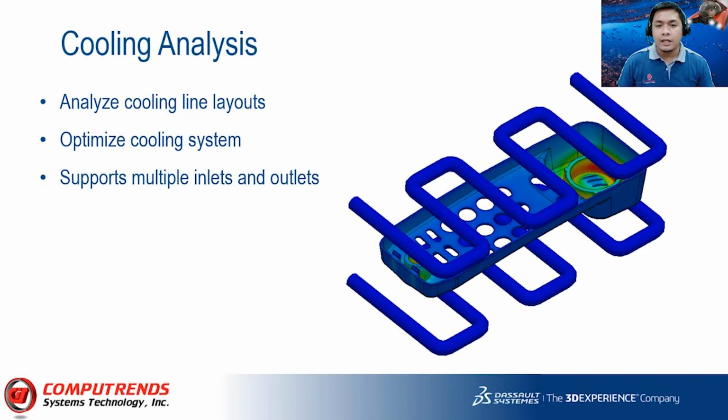Cooling analysis. The cooling function offered in SolidWorks Plastics allows for greater accuracy of temperature prediction and is available in 4 models depending on the level of mold detail available to the analyst. They are responsible for producing a high-quality product with minimal warpage, which is highly dependent on the cooling stage. The uniform assumption of mold temperature is a good way to achieve a good simulation to optimize cooling system design.